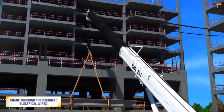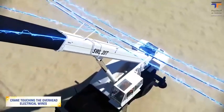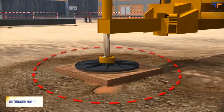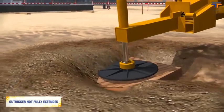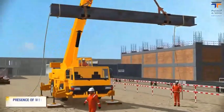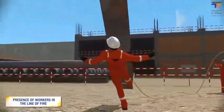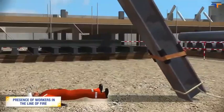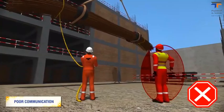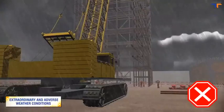Any part of the crane touching the overhead electrical wires, which can result in electrocution. Grounds not being firm and outrigger not fully extended, which may result in tripping, imbalance or trapping of the crane. Presence of workers in the line of fire. Poor communication between banksman and lifting equipment operator. Using equipment in extraordinary and adverse weather conditions.